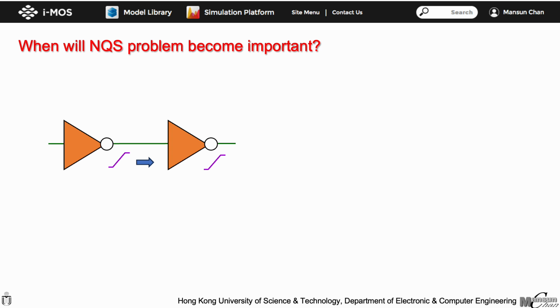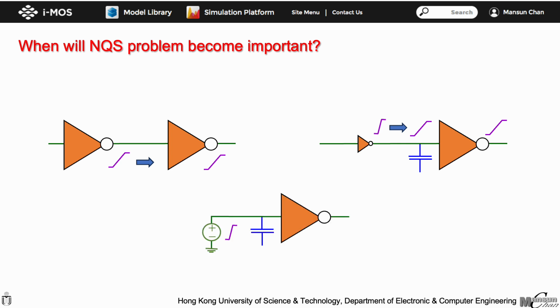For a self-driven circuit, the speed of the input signal is limited by the previous state's response. So a circuit is unlikely to be driven by an input faster than its own response. It will only happen when some very fast switching element is driving a large transistor with slow response. Even when this happens, the effect is usually not very obvious, because the loading capacitor as well as the interconnect delay will slow down the signal at the input.